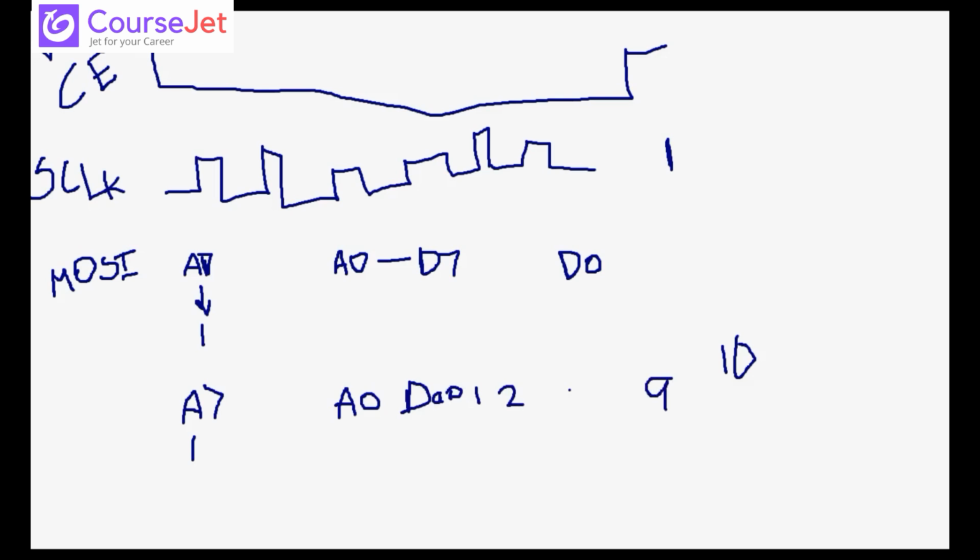Now the question arises: the first address we are providing, at that particular address the first byte is stored, right? Yes, this first byte is stored at this address location. What about the second to ninth byte? Nine more bytes are there. Once you store this data, automatically the address location will be incrementing. You need not say continuously, store my data 1 at this location, store my data 2 at this location.